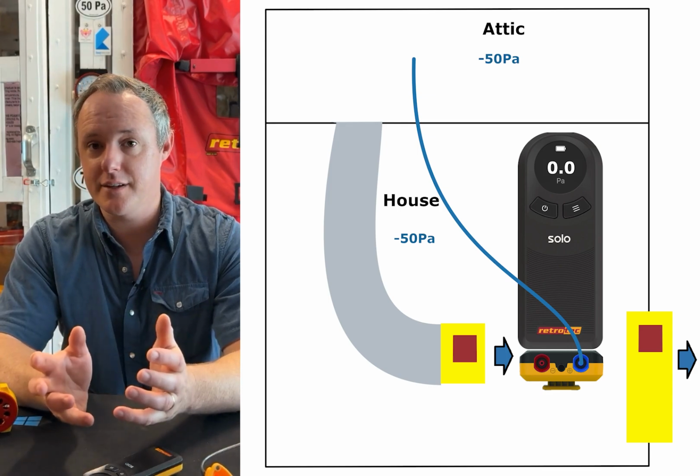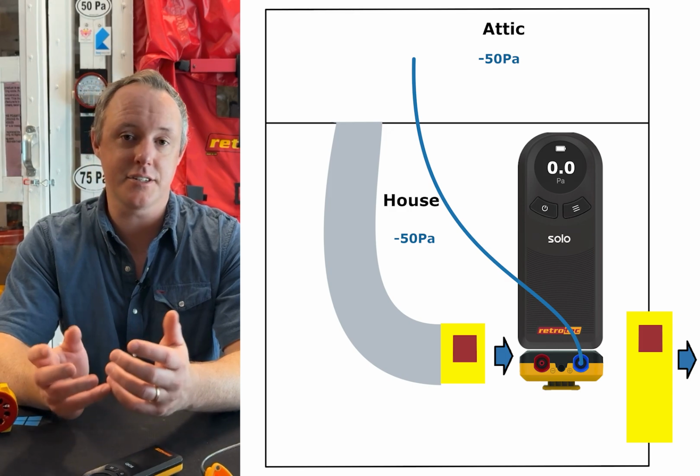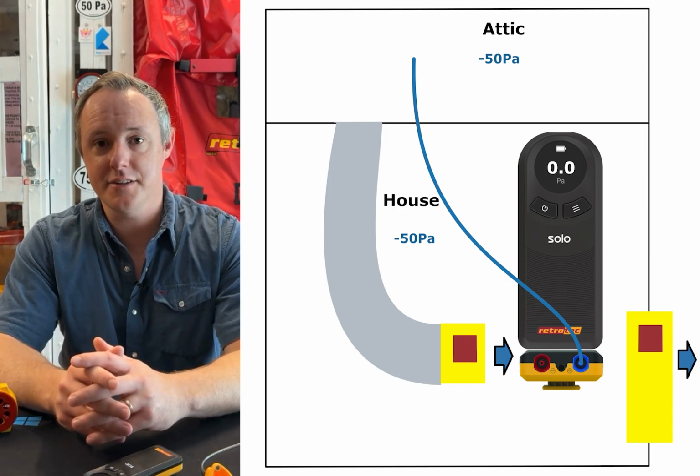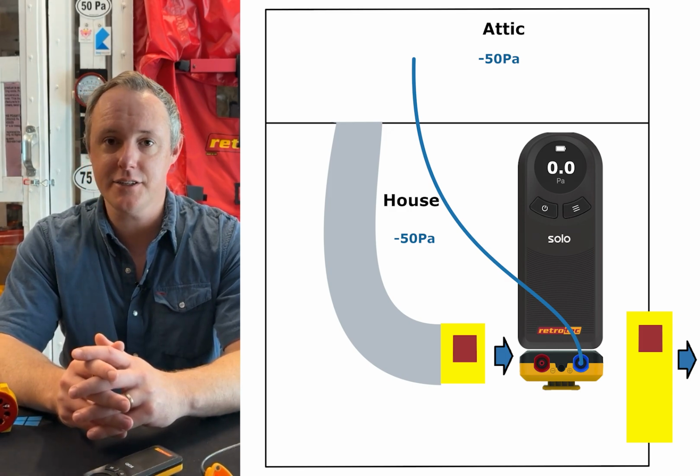And the nice thing about having the attic access in the conditioned space is that the additional fan that you hook up to the attic hatch, you do not need to add that in to your blower door number. It's automatically applied on your main blower door hooked up on the exterior door.